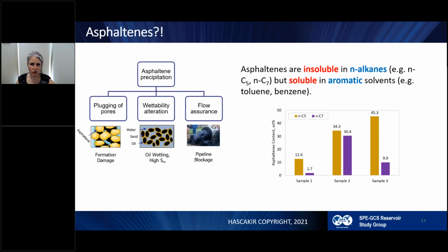And what is asphaltenes really? By definition, asphaltenes are insoluble in normal alkanes, but soluble in aromatic solvents. So you are seeing here 3 oil samples and their solubility in different normal alkanes. What I said, it is insoluble in normal alkane, and I'm treating these 3 samples with normal pentane and normal